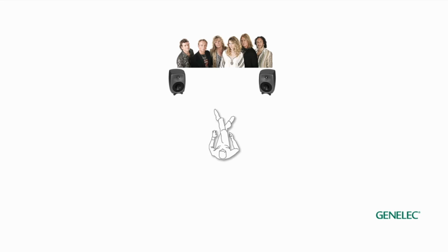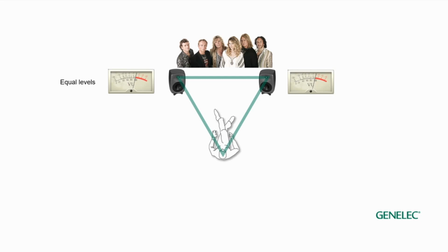All these audio presentation details exist only when we follow the important agreements. For two-channel stereo, we have agreed that monitors are placed at equal distance from each other and equal distance from the listener. This results in a plus-minus 30-degree angle left and right. This arrangement also implies that the level delivered from each loudspeaker is the same at the listening position, and the delay, or the time of flight for audio to the listening position, is the same from both monitors. So we have three parts in this agreement: monitor direction, level alignment, and delay alignment.